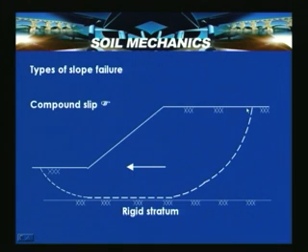So, when this takes place, there will be some settlement here, and because of this, when the failure takes place, heaving of soil takes place here. In this portion, the soil will be subjected to compression, like the way we have conducted the triaxial test to get the soil properties. That means if you take a sample from here, this is the possible failure plane which the soil can experience under stresses. Here the soil will be subjected to tension, or extension here. In this case, this particular interaction almost resembles the way in a direct shear test.